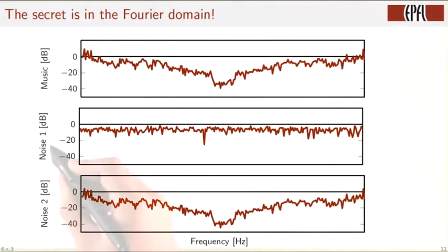Then the first noise, which is 13 dB signal to noise ratio noise, has an essentially flat spectrum across all the spectrum. Whereas the second noise, the clever noise, as you can see, has a shape that resembles the shape of the music. And so when the music has a lot of Fourier energy, we can add some noise, whereas when the music has very little energy, we put very little noise. So that's called noise shaping.